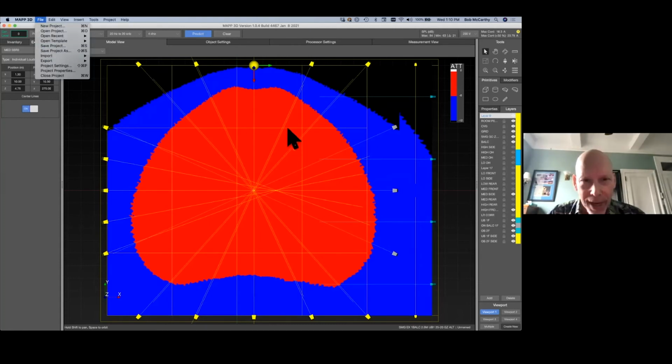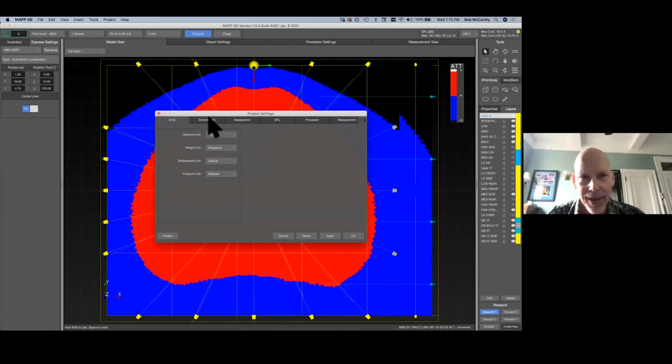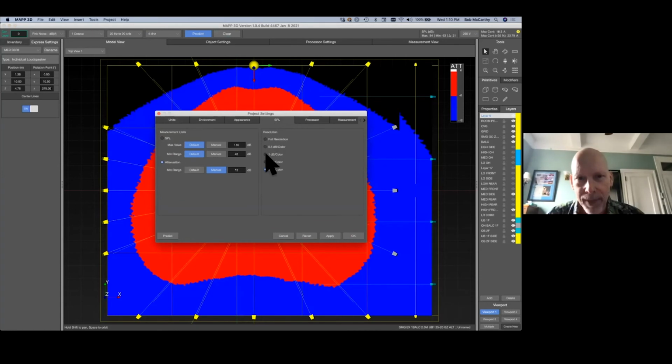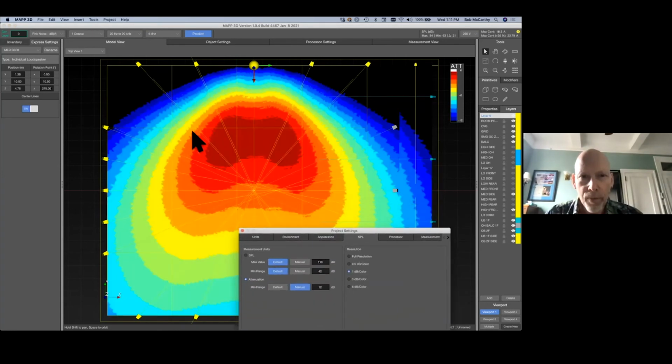Well, as I cross the Go zone line, I'm going to make this into 1 dB per color. So we'll get a little more detail. So there is 0, 1, 2, 3, 4, 5, 6. You get the idea. So if you look at where the next speaker is aimed, effectively, it's crossing the line, it's still in the 0 range. By the time this one crosses the line, it's 1, 2 dB down.